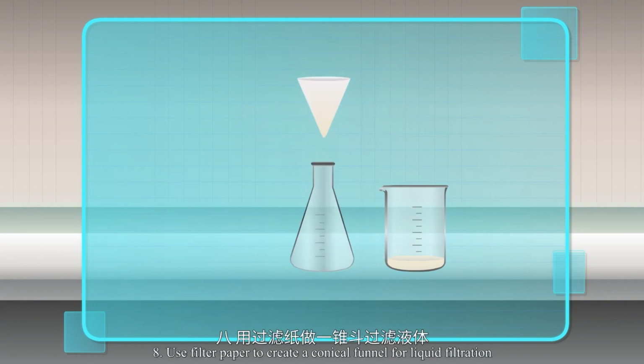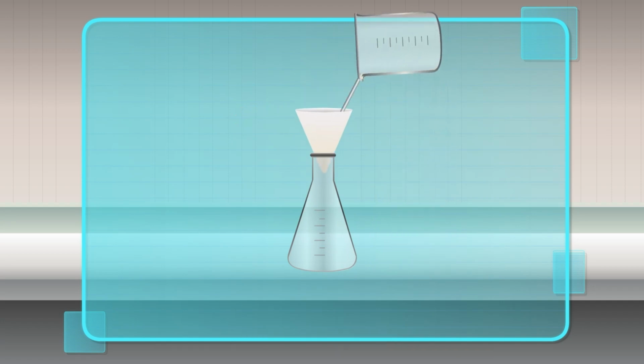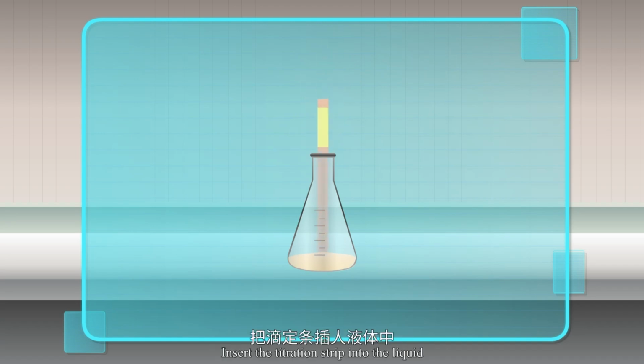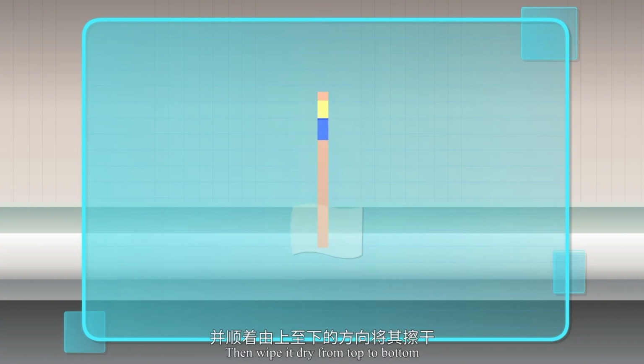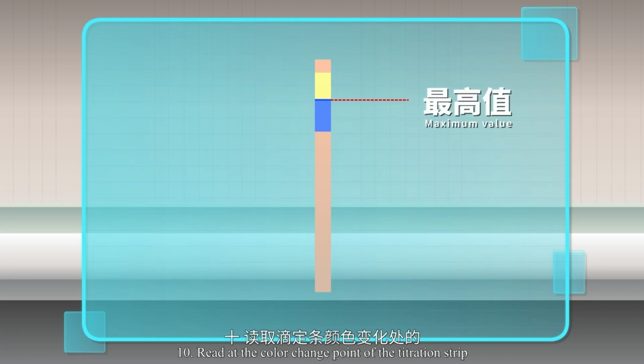Eighth, use filter paper to create a conical funnel for liquid filtration. When pure solution infiltrates the funnel, insert the titration strip into the liquid. Ninth, wait until the titration strip tip, the horizontal yellow strip, turns blue. Remove the titration strip, then wipe it dry from top to bottom. 10. Read the maximum value at the color change point of the titration strip.